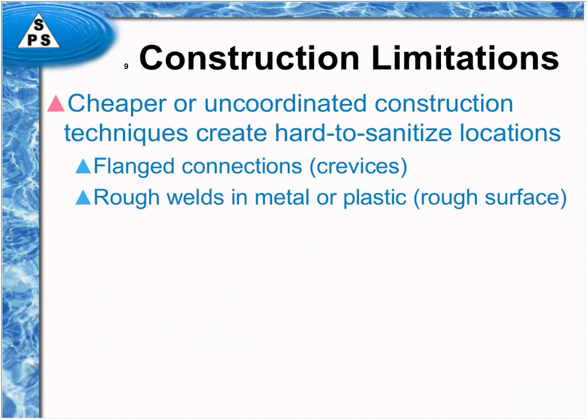The rough welds that may actually be created in the process of putting together even a stainless steel system that's poorly welded, but often plastic surfaces, especially PVC, where they're glued connections, there are very rough surfaces that are created, and those rough surfaces tend to be very difficult to sanitize.